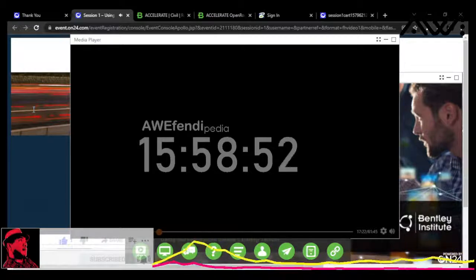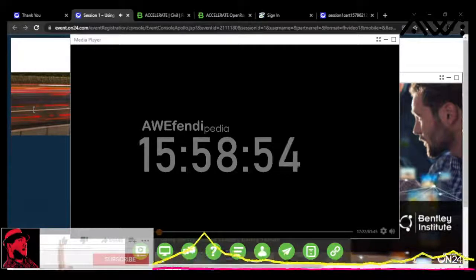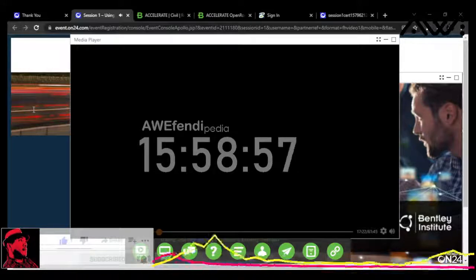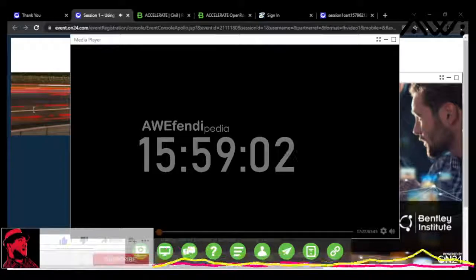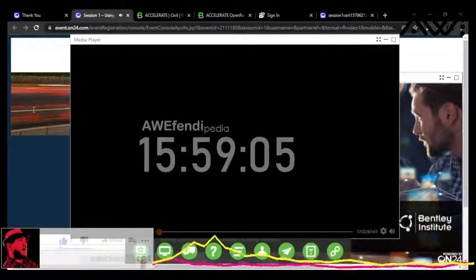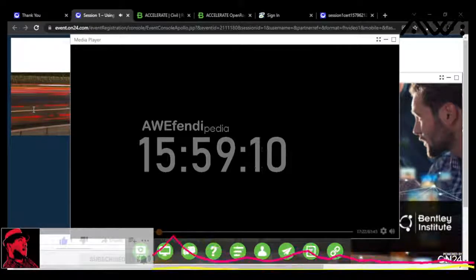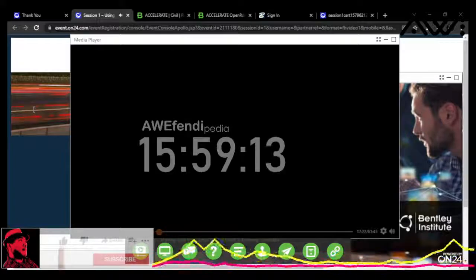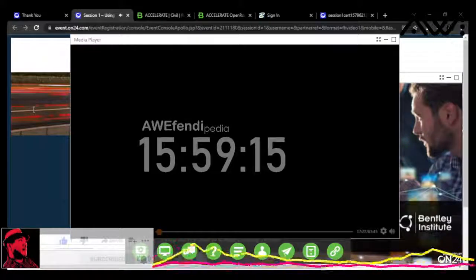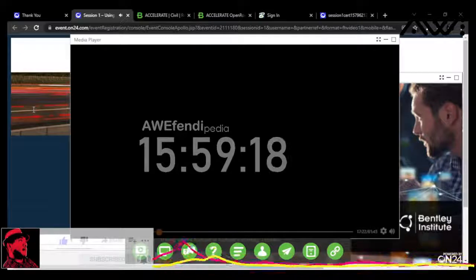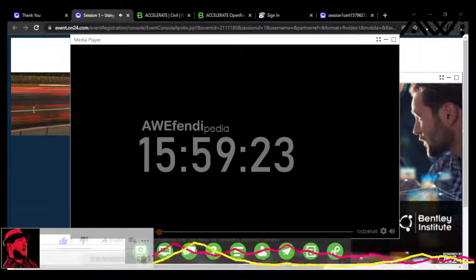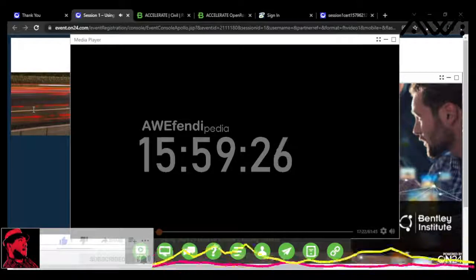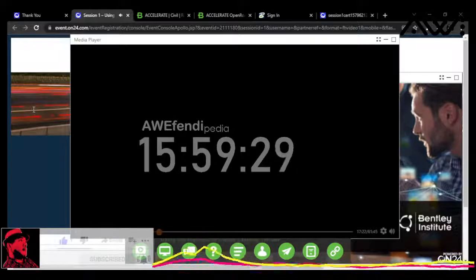The first thing I'm going to do before I finish out looking at the settings is I'm going to go ahead and create a field book in this DGN file. And what that'll do is that'll copy in the rest of my settings from the DGN libs into my survey file that we can look at. So I'm going to go down here to the survey tab in my Explorer, and I'm going to expand survey data, expand the model that we're in, and I'm going to right-click on field books, and we're going to create a new field book here. So we're just going to click New. And that creates a field book ready to receive the raw data.